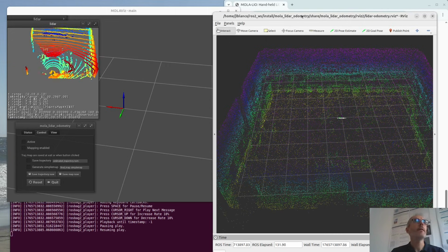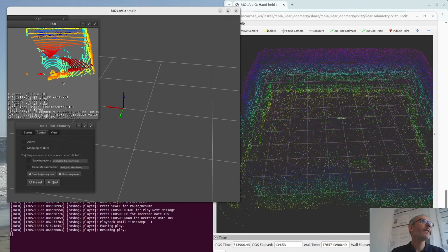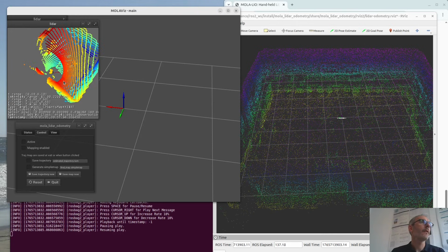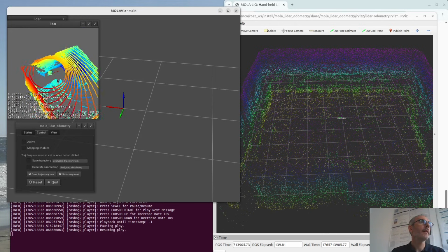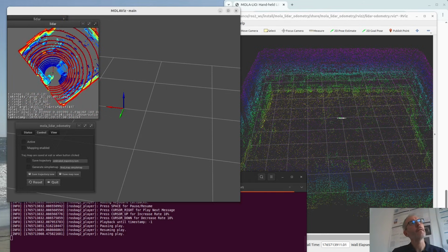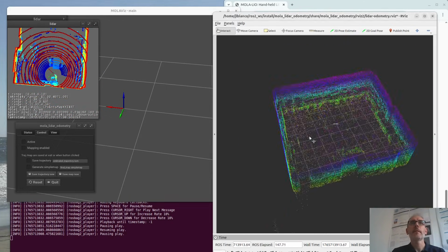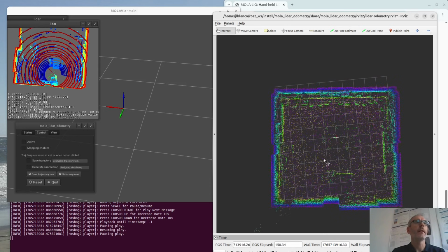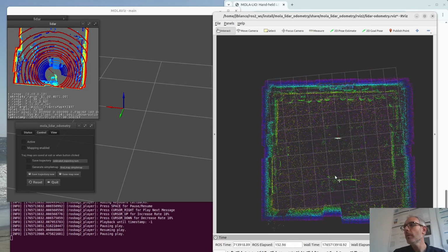Let me check this a little bit. Okay, it's rotating like that. Okay, so I will stop this here. Right now I know where the sensor is in the room. It's something like this. The room is like this, and the sensor is at the bottom. So I will just use the standard topic for this, which comes from ROS 1 times. This button here is the 2D pose estimate. It's the same one that you could use for a particle filter algorithm. So just click anywhere here.